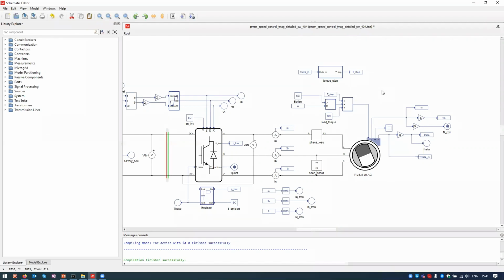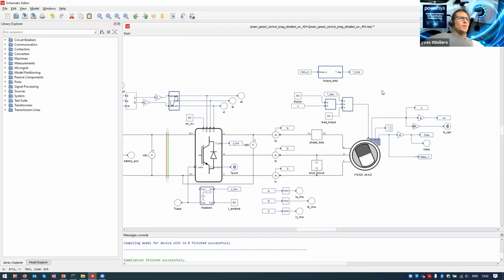We could see that if there is a small error in the current sensor, then when you reach the limits of your drive's performance, you can easily have a trip occur. We were really able to reproduce that type of behavior on the HILS as well. That's one thing that I found really interesting there. Okay, thank you.